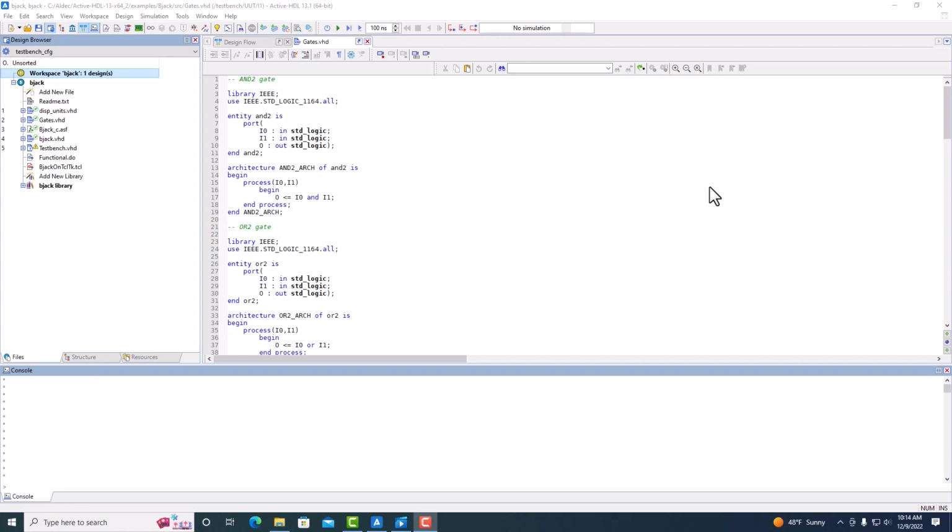Linting is the act of performing design rule checks on individual units or files and can be run in the early stage of writing your code or when applying some quick fixes. For a comprehensive check, full linting must still be run as it checks the full design hierarchy to catch more complicated violations. You can learn more about that form of linting from our ALINT-PRO demonstration on our channel.